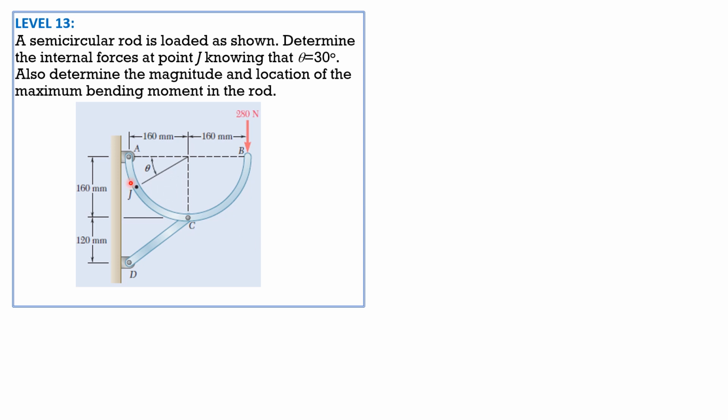By looking at the frame and rod, we have a two-force body, which is this member here, CD. There's no load in between. Therefore the force in D is equal to the force in CD, and the direction of force is along CD. So call that reaction at D as PDC as shown. It is directed along CD. Then at A we have AX and AY.